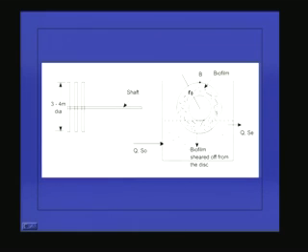Naturally the biomass will be growing in this circle. This portion is not exposed to the wastewater, so there will not be any growth of biomass. So you will get a ring-shaped biomass growth. Here also this is the wastewater, and because oxygen is transferred from the atmosphere to the wastewater, some growth will take place in the suspended system also.